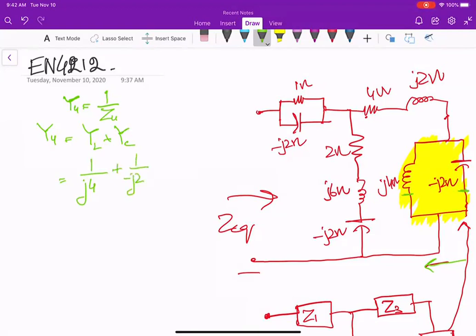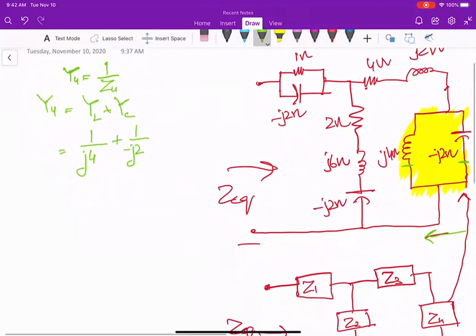I told you that if they are in ohms, they are in impedance form, and to find the admittance, we need to take the reciprocal of that. If you see S, the unit of susceptance or conductance, then they are in admittance form. Okay, so let's try to find that.